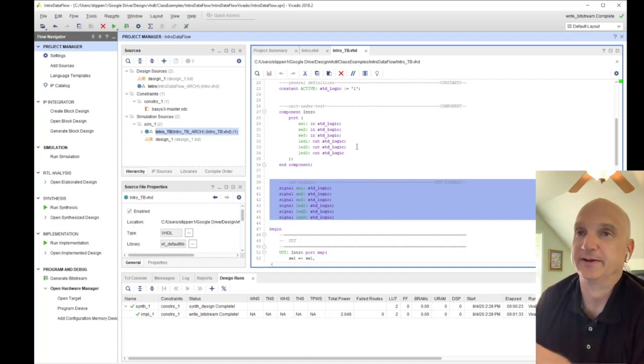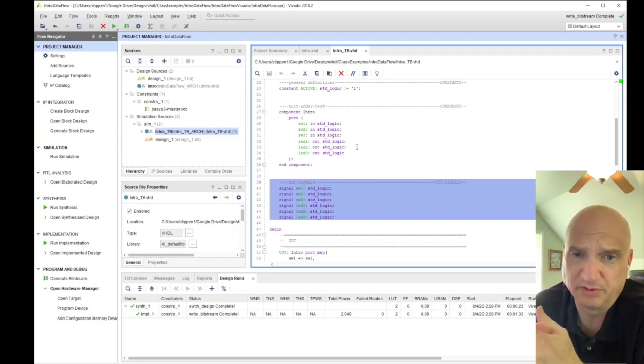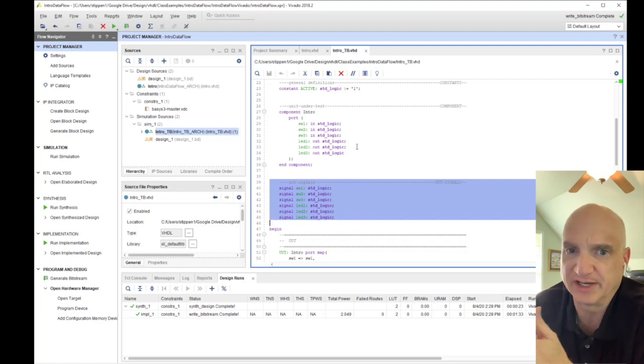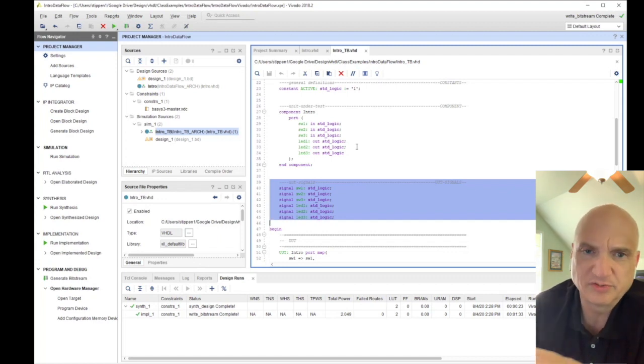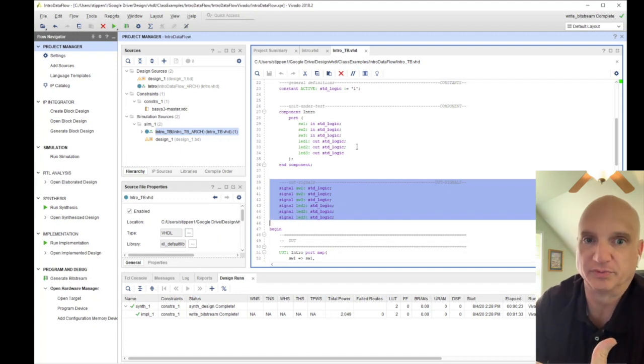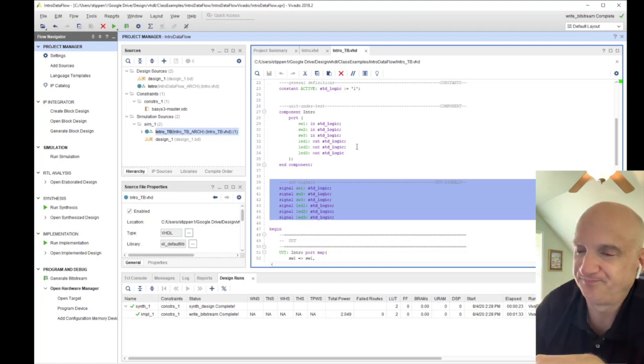This means you're less likely to have issues later on when you're debugging to figure out what the signals are. So I wouldn't use two separate types of names. I would use the exact same names, because remember, the signals are inside the test bench component, not inside your intro component. Those are defined internally inside the intro component.